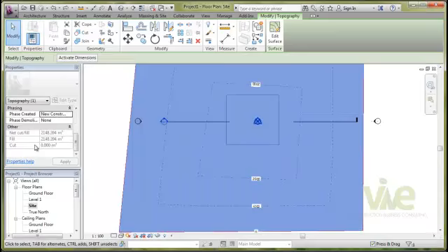Seems okay to me. Now you can see that there's a net cut/fill value that's been updated. This is due to the fact that we have added that building pad. Now you can see that the cut value is still at 0. This is because the building pad is still above the existing topo surface.